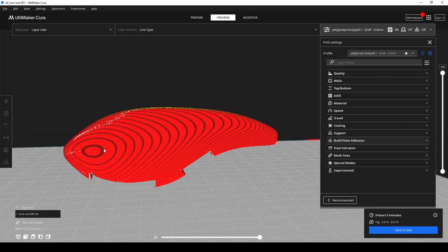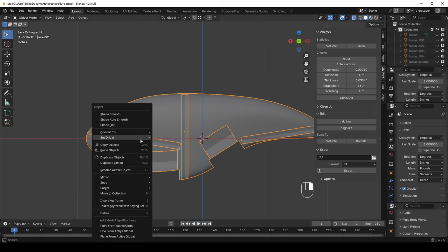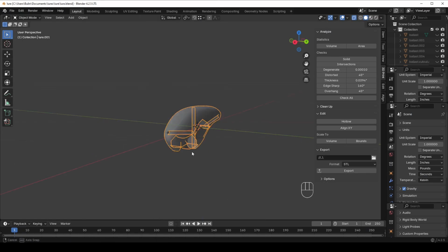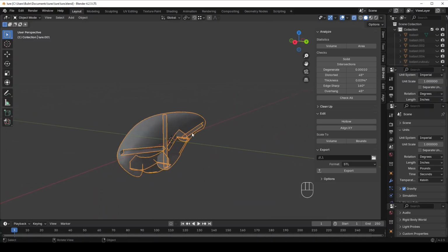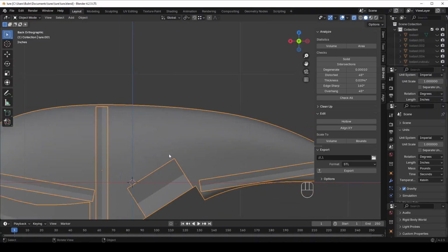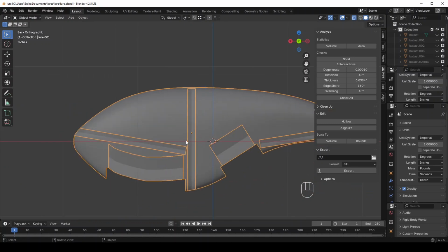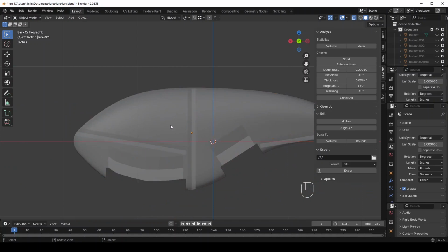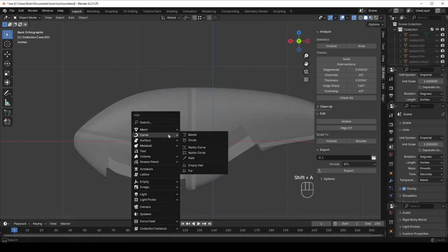In our previous videos, we've been designing our own lure from scratch in Blender. There's a link to that playlist in the description below if you have not been following along. Where we last left off in that video, I realized that I forgot to show you how to add the lure eyes if you want some eyes in it. The eyes that I have on hand are 8.5 millimeter, so we're gonna create those real quick.